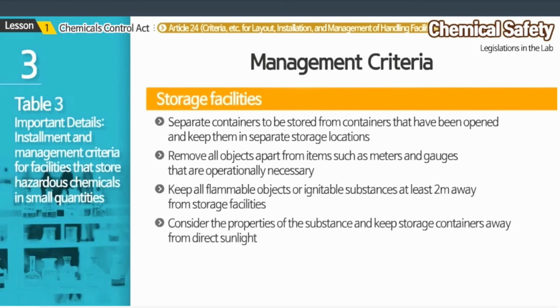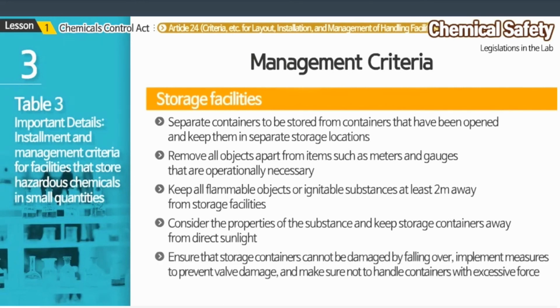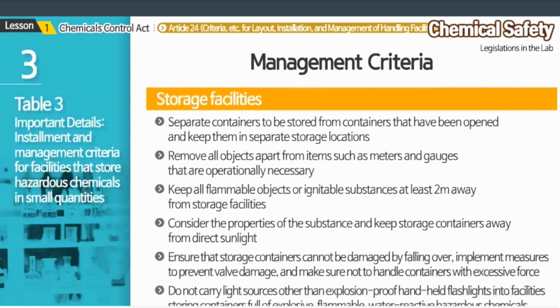Fourth, you must consider the properties of each substance and keep storage containers away from direct sunlight. Fifth, you must ensure that storage containers cannot be damaged by falling over. Implement measures to prevent valve damage, and make sure not to handle containers with excessive force. And finally, you must not carry light sources other than explosion-proof handheld flashlights into facilities storing containers full of explosive,